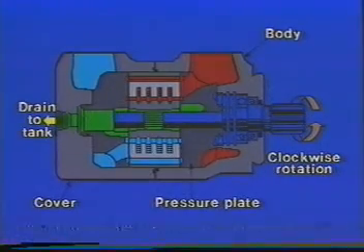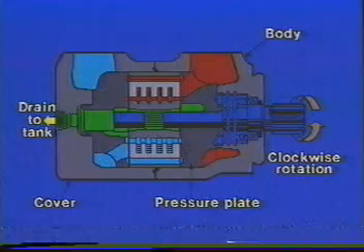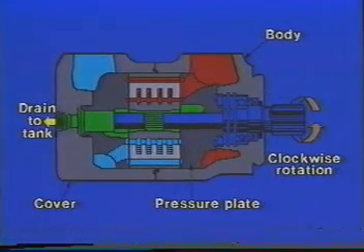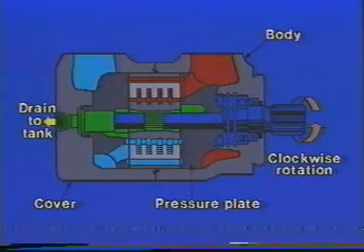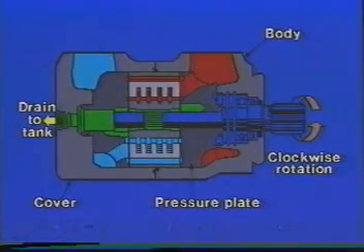External draining in this unit is accomplished through a port in the cover. Just as with a vane-type pump, if we want to change motor displacement in a given frame size, all we do is simply change the cam ring to one that is wider, larger, or smaller in diameter. Let's switch over now to a study of piston motors.